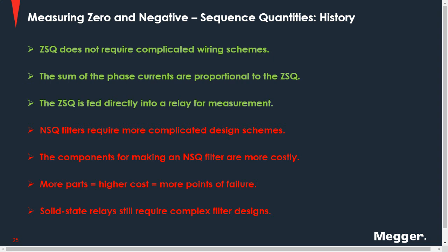We saved a lot of space, a lot of real estate with the solid state relays. However, you still didn't have the ability to perform a numerical analysis and to find the magnitudes to measure these negative sequence quantities. So you still had to implement a rather complex filter design.